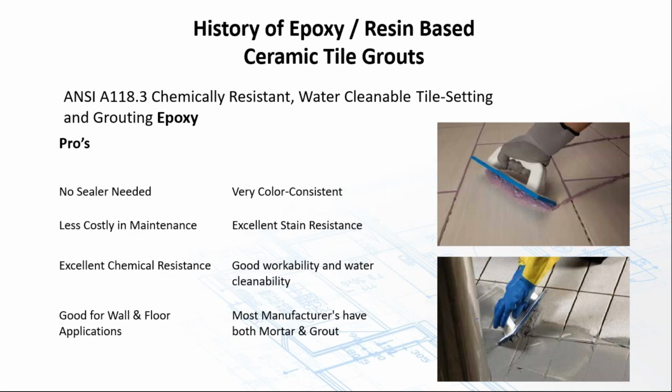The pros of these highly water cleanable epoxy grouts: again, an epoxy grout, no sealer is needed, very color consistent, less costly in maintenance because you're not sealing it, and staining comes off of it. You spill the ketchup on it, spill the coffee on it, or have problems in the restrooms, you're not going to end up with a stained grout. Good for both wall and floor applications.